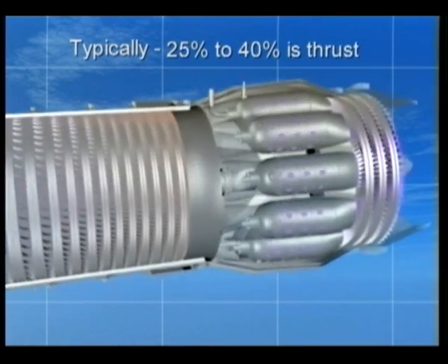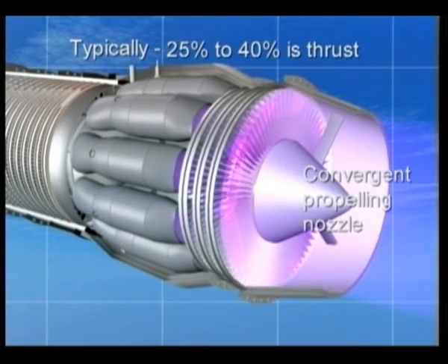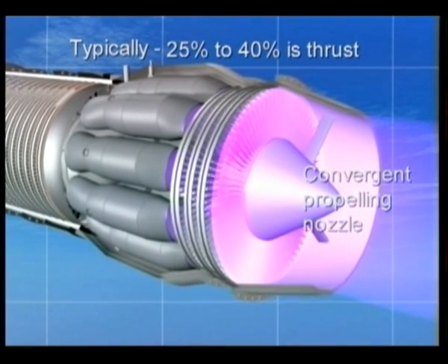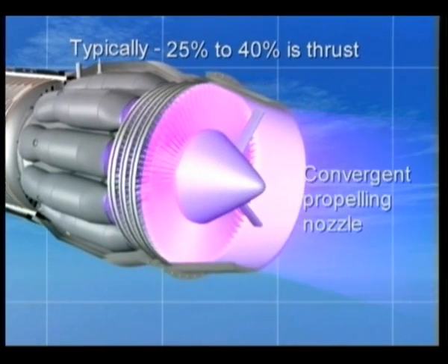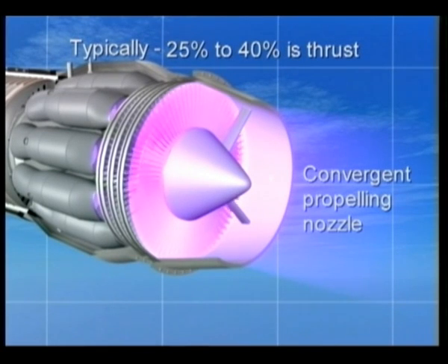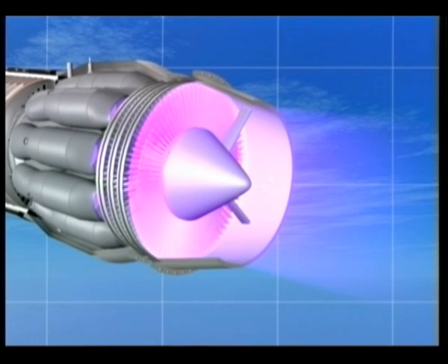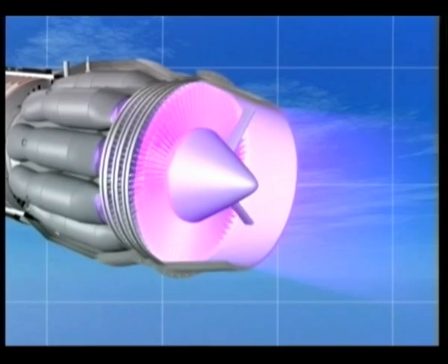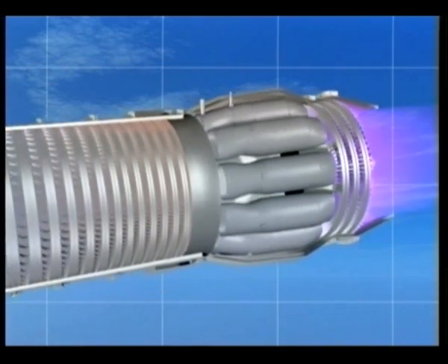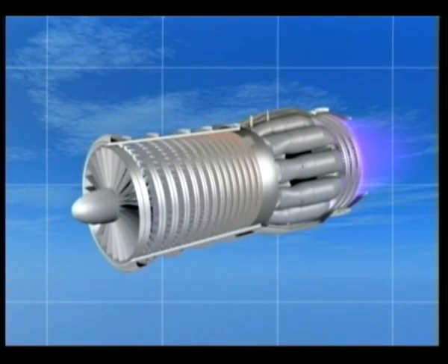The remaining 40% of the energy after driving the turbine and the compressor is used to form a high-speed jet, which has a substantial residual pressure. This jet passes into the exhaust cone to emerge close to atmospheric pressure at the orifice. The jet not only has kinetic energy owing to its velocity, but also has substantial heat energy. However, the heat energy is released to atmosphere and is consequently wasted.